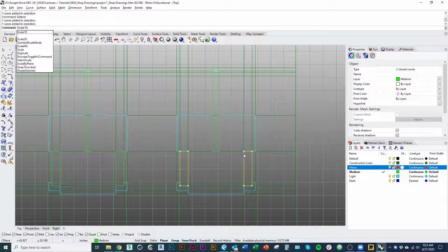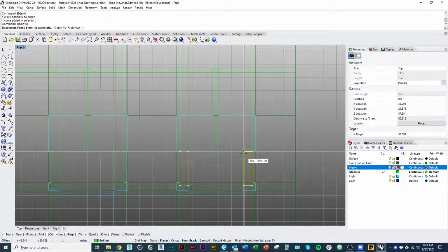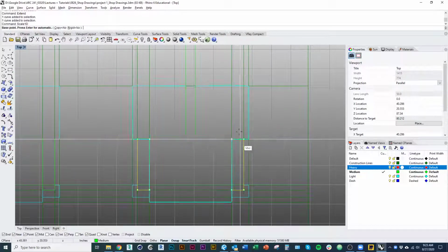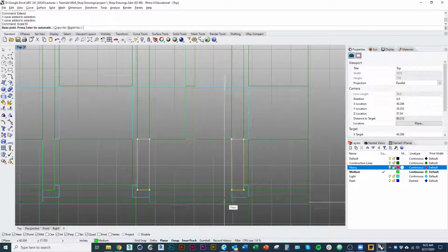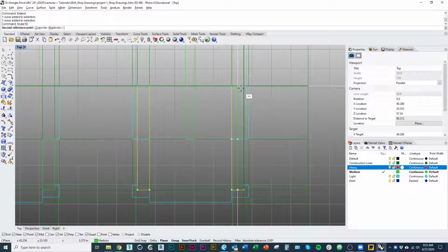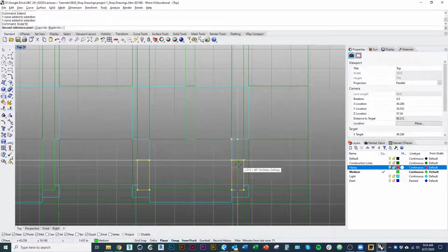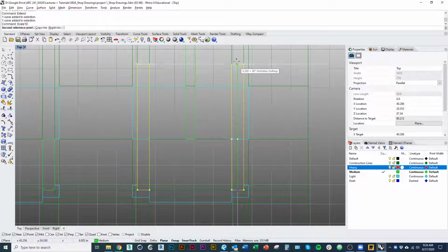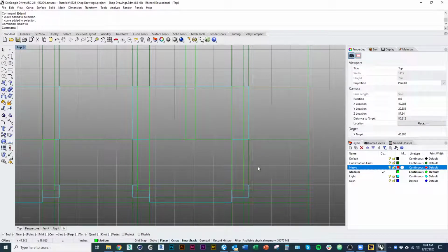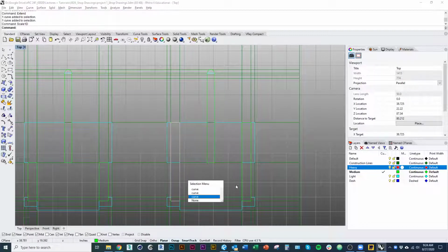And for example, if I want to make something longer but not wider by proportion, I can use scale 1D, which stands for one dimension. And in order to scale something to a specific length, right? So I want to make it longer in this dimension, but not wider. So I'm going to snap my two points to that dimension. So now you can see I'm just scaling it in that dimension, I'm just making it longer or shorter. And I'm going to snap to up there. And there we go. So those are the sides of our box.